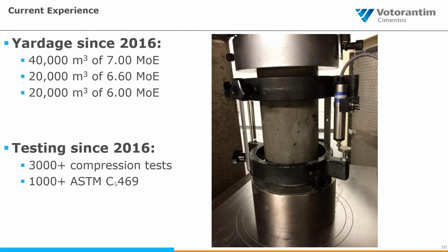And then one specimen is broke, or 2 specimens are broken. Those compressive strengths are averaged. You take and run the cylinder up to approximately 40% of the overall compressive strength, and you do it within this rig. So that extensometer you see on the right here simply measures as the cylinder is loaded how much of a movement change you have. And I'll show you later the other secondary portion, which includes the Poisson's ratio. But this is the test, and there's a lot of very exciting tests within the construction industry. Unfortunately, modulus of elasticity is not one of them. You run the cylinder up and you run the cylinder back down in a controlled load rate, so there's no explosion. There's no big fancy end of the test. It's quite boring in case you ever actually witness it.